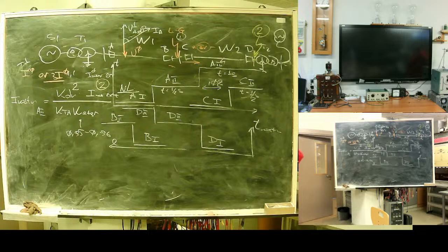non-symmetry. If you take a look on the network, distance between wire and ground are different for phase. So capacity is not uniform. This means that in normal operation regime, you will see some current. The network isn't absolutely uniform.